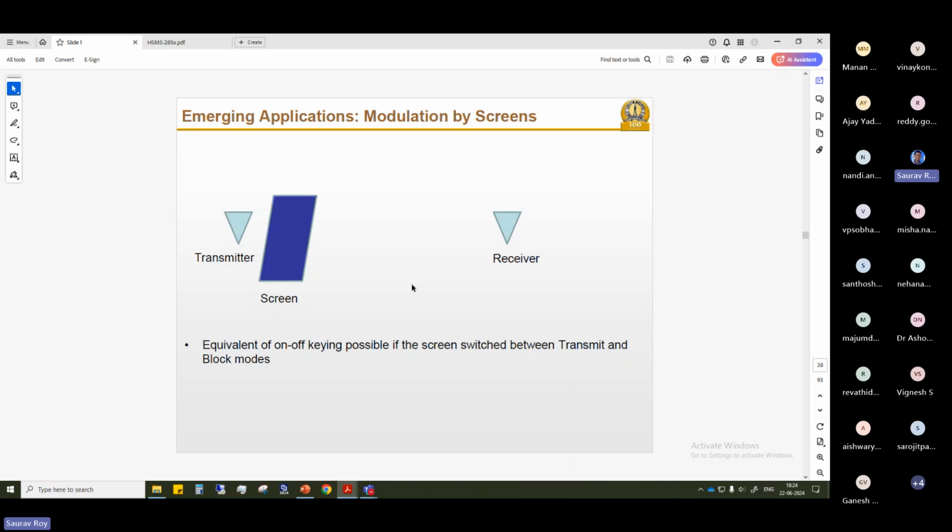Similarly, another modulation scheme is spatial modulation. So spatial modulation is also similar, where we have the normal communication scheme like QAM, QPSK in combination with this SSK, shift keying. So together they bring a spatial modulation scheme. So you use a combination of multiple antennas to transmit along with your signal, QPSK or QAM. So that will bring additional information at the receiver. Okay. So that is one.